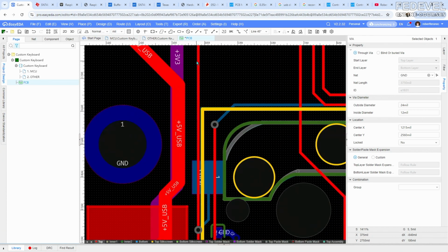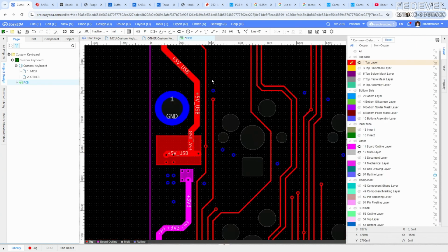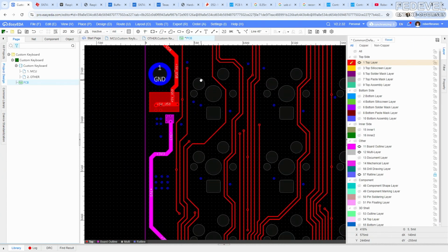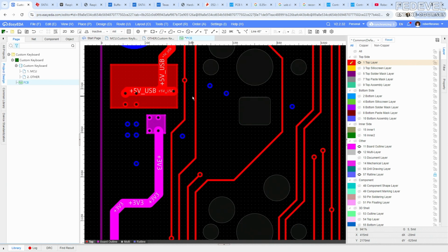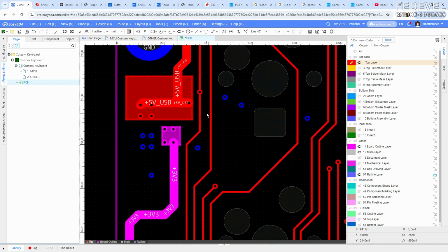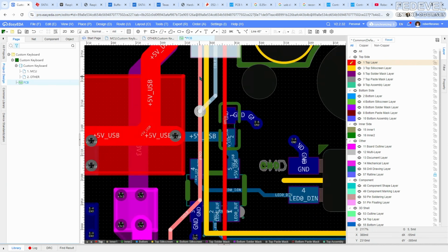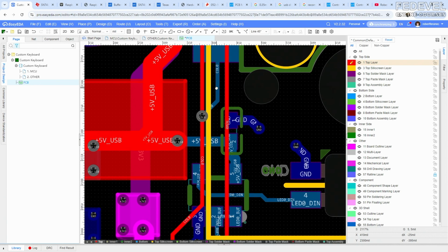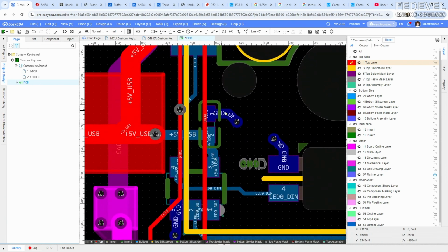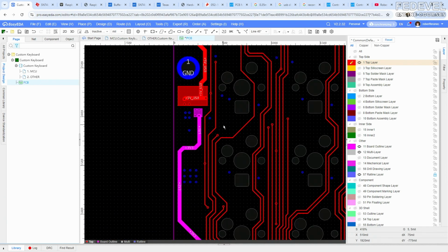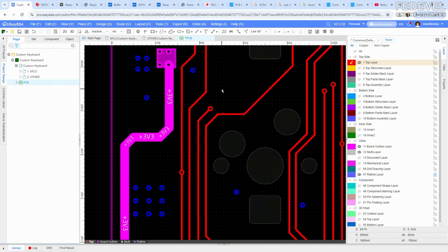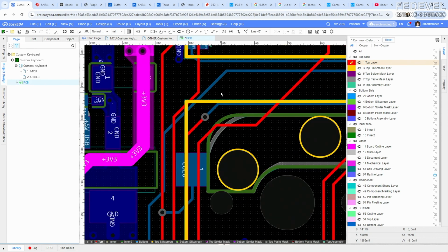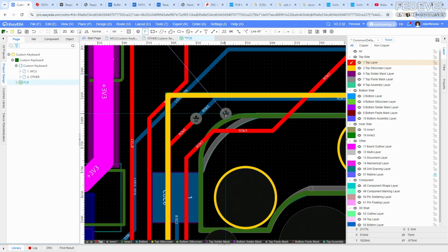And these, very simply to say, these vias are helping to control the path of return currents for the signals which are traveling through the tracks. I'm trying to double check all the places where we can easily place these vias, and also when or where we need them.